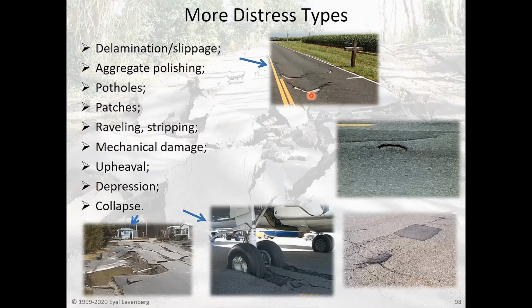As you can see here, these moon-like shaped cracks appear, and the white below the black is actually the old asphalt surface, or maybe an old Portland cement concrete surface that was exposed. This is very common in areas of braking and accelerating, in combination, of course, of bad bond between the layers.